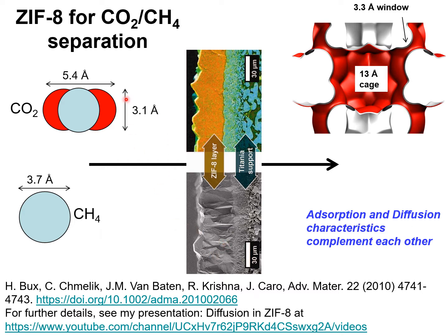The important advantage of ZIF-8 for CO2 methane separation is both adsorption and diffusion complement each other, leading to high permeation selectivities in favor of carbon dioxide.